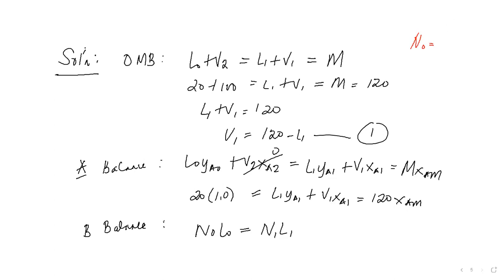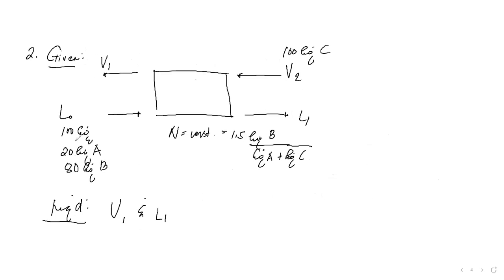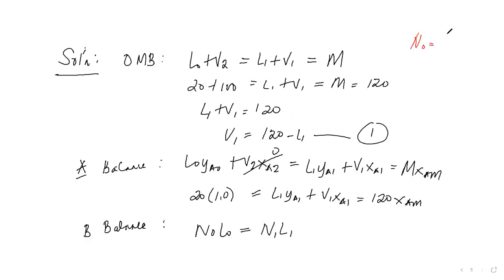Your solid in the feed is 80, and your A plus C in the feed is just 20 because you don't have any C. So in this case, you will have 80 over 20, which is 4. Okay? Your L0, we know our L0 is equal to 20. So automatically, the 20 times 4 is actually the 80, which is your solid.